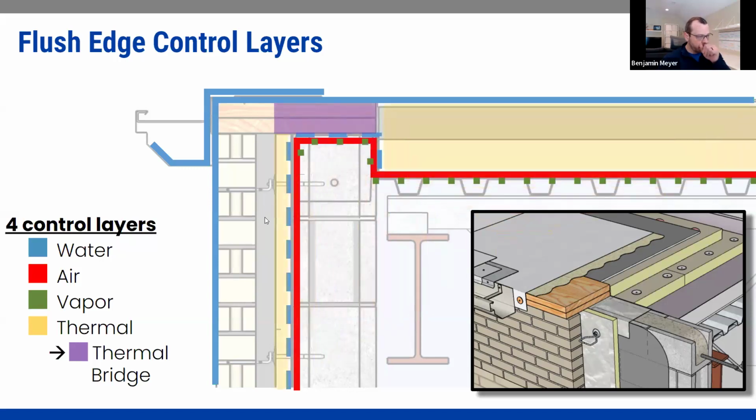And the last one is insulation. So at the roof level, we have 2 layers of continuous insulation at the roof, staggered and offset as it should be. And on the wall, we have continuous insulation on the outside. So again, protecting the CMU. And I have this purple here at the blocking for the parapet.